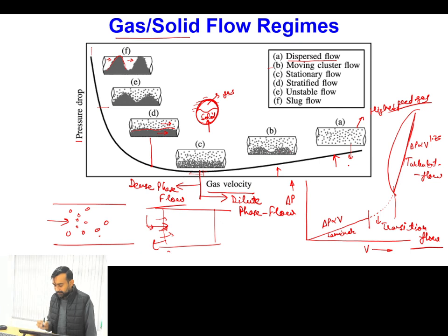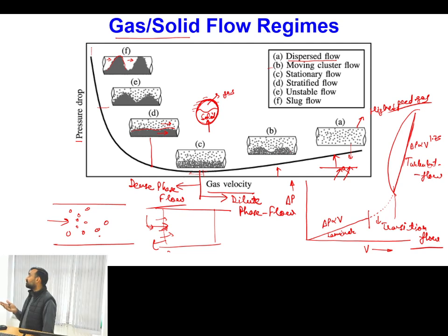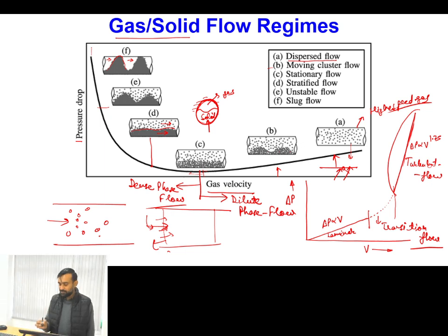So when high velocity solid particles strike the wall, ultimately they lead to erosion of the pipeline. High momentum of particles striking the wall of the pipe leads to erosion of the pipeline. Because of this, pipeline failure will take place at a faster pace.